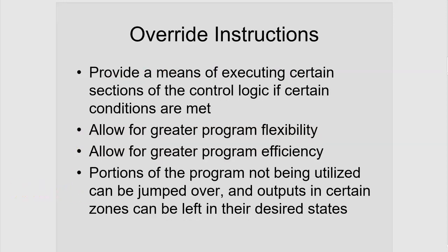So let's talk about override instructions. They provide a means of executing certain sections of the control logic if certain conditions are met. So these are all conditional instructions. They allow for greater program flexibility and greater program efficiency. And the reason they do that is because, this last point here, portions of the program not being utilized can be jumped over and outputs in certain zones can be left in their desired states.